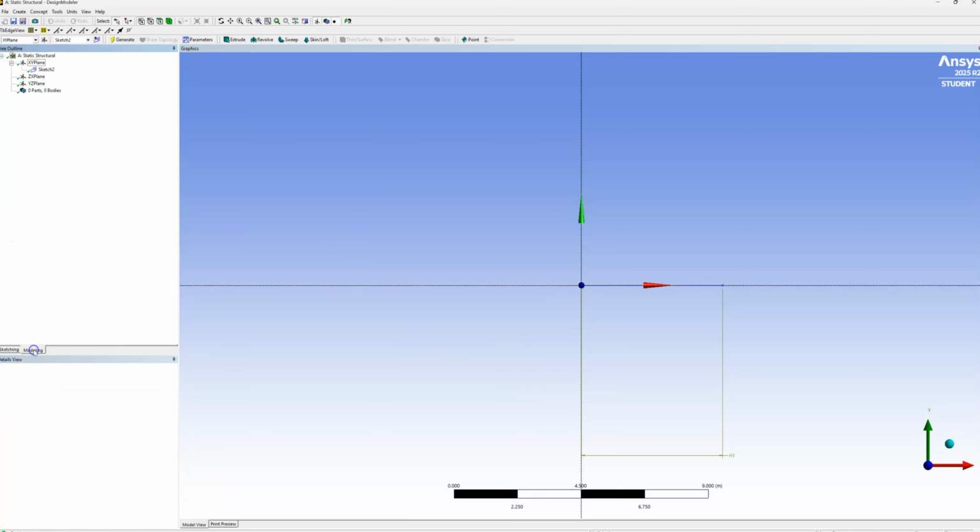So we go back into the modeling interface, and we will see Sketch 2 appears up here. What we're then going to do is create a line from that sketch. So we'll see lines from sketches here. We have to tell the software that this is the line that we want to use. So we're going to select the line and hit apply and generate. And you'll see then we have created a line body, which is highlighted in yellow here. This is essentially the axis around which we're going to create our geometry.